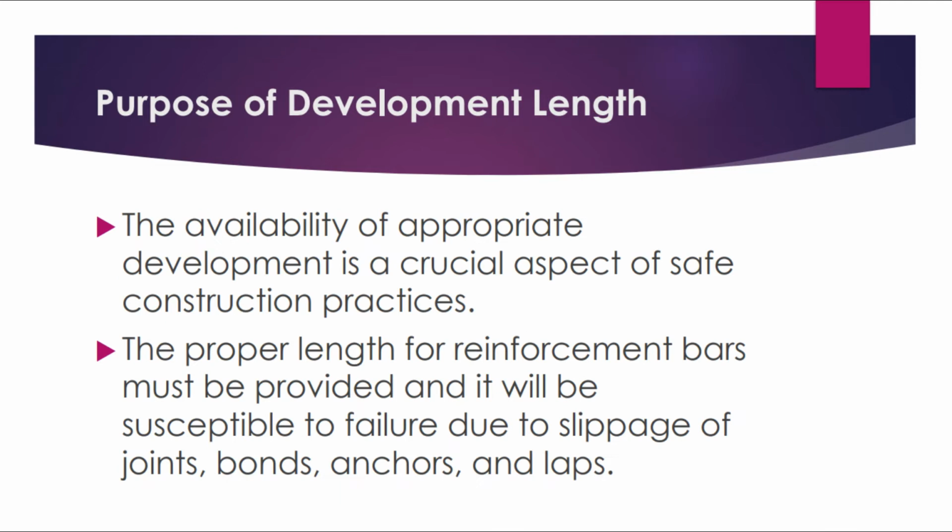Purpose of development length. The availability of appropriate development length is a crucial aspect of safe construction practices. The proper length for reinforcement bars must be provided, otherwise it will be susceptible to failure due to slippage of joints, bonds, anchors, and laps.